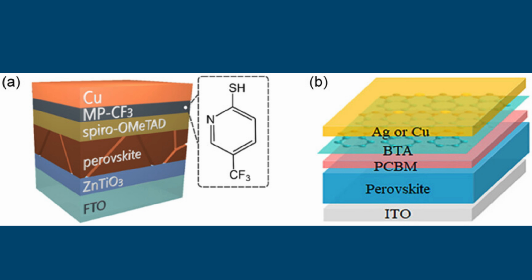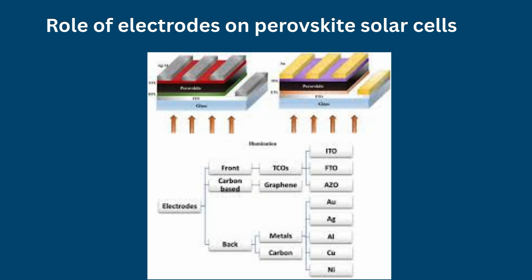For example, copper electrodes exhibit good stability with minimal diffusion into perovskite layers, while aluminum electrodes enable efficient inverted PSCs with competitive PCEs exceeding 17%. Alloy electrodes, for example, silver-aluminum electrode, further enhance thermal stability and interfacial properties.